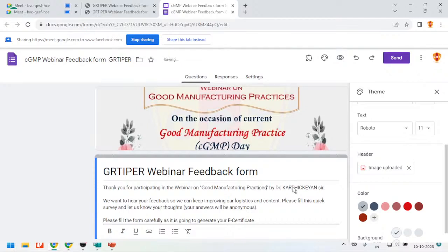This is where we will do the washing, cleaning. Like this, all the areas wherever, in the injectables area, dry powder parenterals, liquid parenterals, even the tablets and capsules area, all these FBD bowls, all the coating solution containers, all vessels have to be cleaned and taken care of. This is the procedure we follow in the industry. So we will be doing this washing and cleaning of the equipment or vessels, all the things.